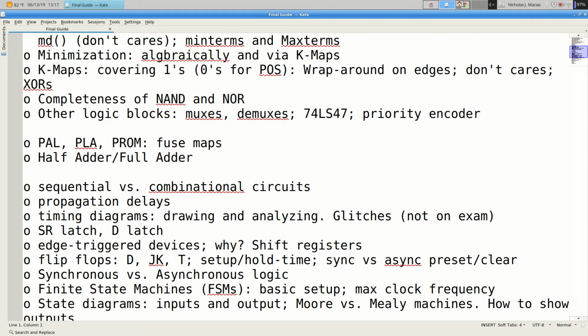And everything we've talked about is synchronous logic, so we've always had a clock in our system. We can do asynchronous design. It was popular in the 80s, it got popular in the 2000s, it keeps coming back, because the clock really kind of slows us down. It says we can only do things 3 billion times a second if it's a 3 gigahertz clock. You can do asynchronous, but then you've got all the problems with glitches and timing issues that we've been trying to avoid by having a clock. But if you can take an async course sometime, go for it if you like this stuff, because it's cool.